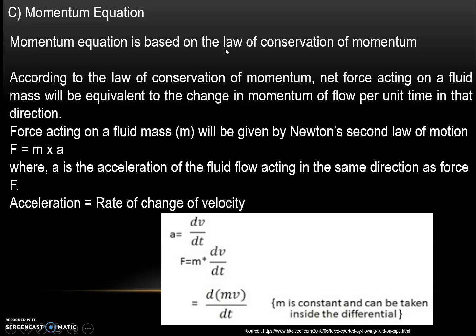The momentum equation is based on the law of conservation of momentum. According to the law of conservation of momentum, the net force acting on a fluid mass will be equivalent to the change in momentum of flow per unit time in that direction. Force acting on a fluid mass m will be given by Newton's second law of motion, that is F is equal to m into A, where A is the acceleration of the fluid flow acting in the same direction as the force F. Acceleration is nothing but the rate of change of velocity. So, A is equal to dv divided by dt.